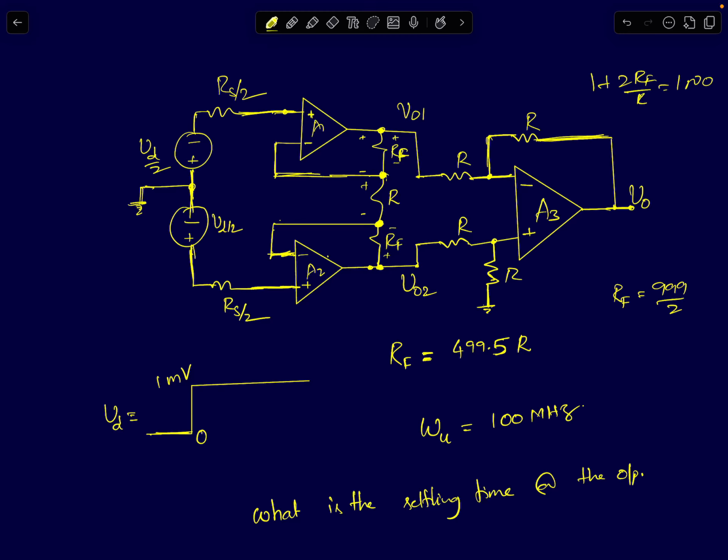Hi everyone. Now that we have finished our discussions on instrumentation amplifiers, I thought I'll discuss a few problems on instrumentation amplifiers, something that's based on what we discussed so far. So shown here is an instrumentation amplifier with a second stage gain of 1. If you see, the resistors here are R and this is also R and R. So the second stage subtractor's gain is just 1.